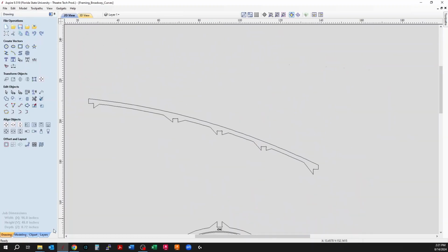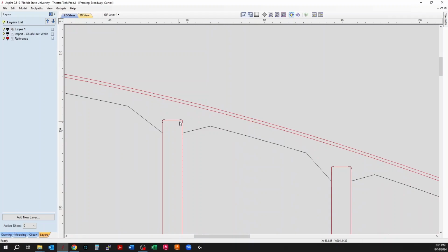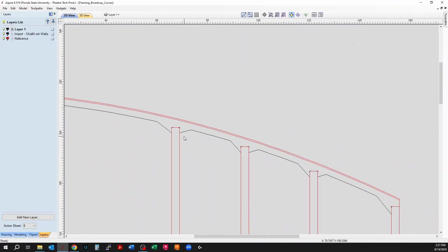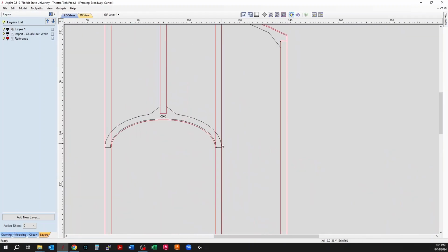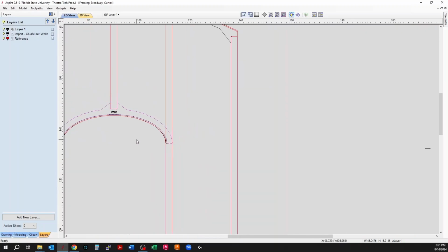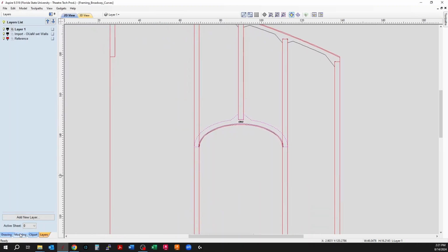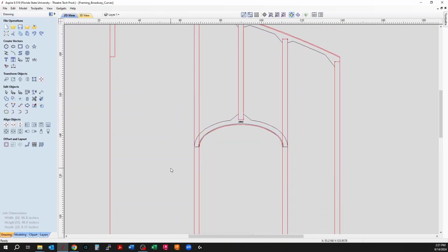And so let's take a look at that real quick before we go any further. And there it is. So you got your square shape going into place, and so it'll get a nice tight fit. All right, so the next bit will be to do a let in over here, because right now it's going through the whole frame, which, okay, you want it to come into the frame, but you want to have a way of like locking it together. So we'll probably do some corrugated fastener bit there, and so we just need a little bit of structure to allow us to do that.